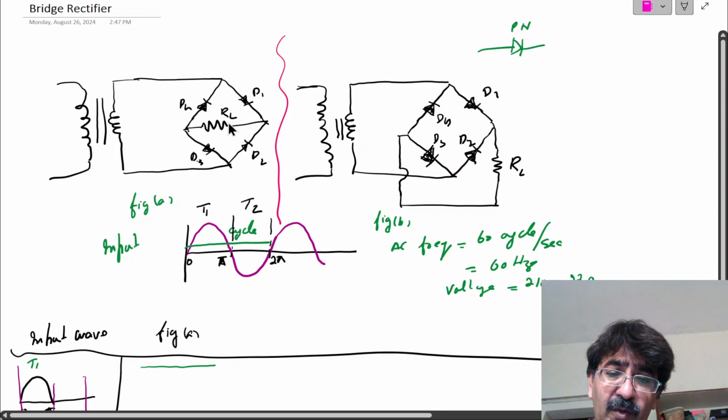So the P side is receiving the signal which has dropped in value due to the load resistance, so it has a lower value, but the N side will receive the higher value, which is coming directly from the transformer. So the P part will be lower and the N part higher. So this will also be a reverse bias, an open circuit, for T1.